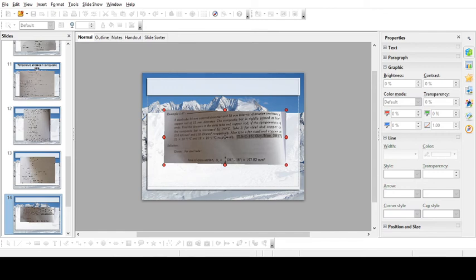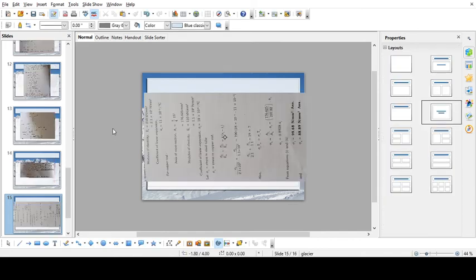So pi by 4 into 24 square minus 18 square. That one will give a value of 197.82 mm square. Next, the diameter of the copper rod is 15 mm. Now the area of the copper rod is simply pi by 4 into 15 square.